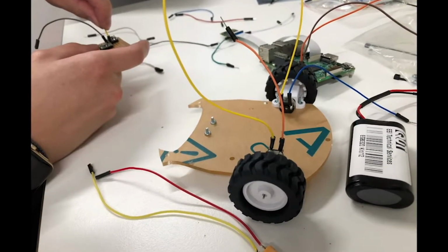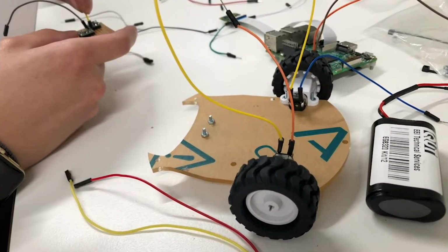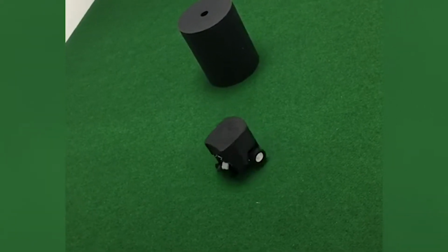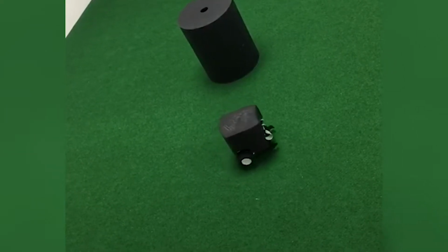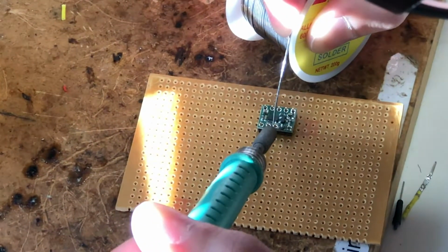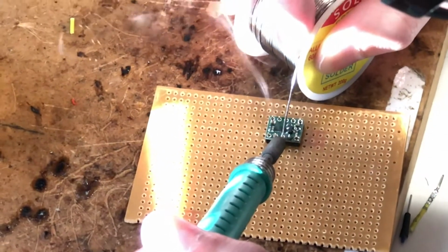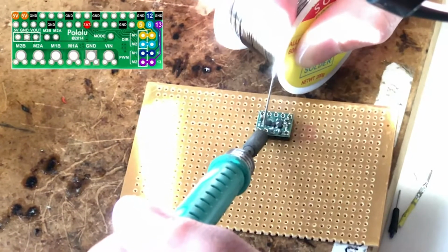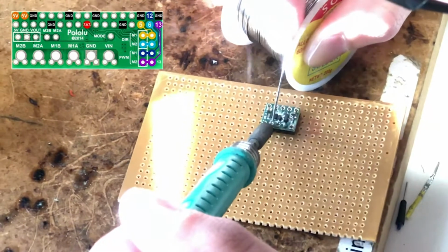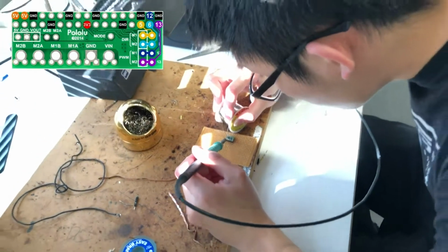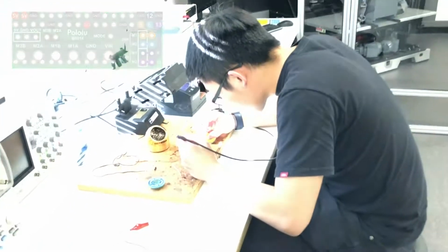Reserve 2 holes at each side of the indentation for dribbler mounting. In the drive system, using 2 motors at each side to achieve differential kinematics. Control the motors by PWM, achieve speed change, turning, and rotation. The PCB board on the robot consists of 2 motor drivers and a voltage regulator module pin. The internal motor driver can apply PWM and direction control for 2 motors. The voltage regulator can supply power for the Raspberry Pi. It can step down the voltage from the battery.